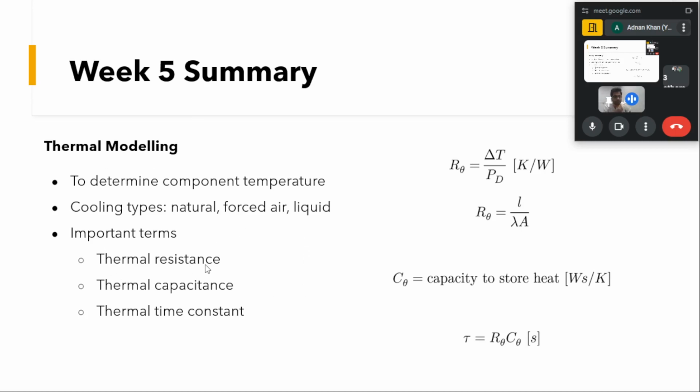First is thermal resistance. This is the thermal resistance of the device. If we have a device or the heat sink, in the data sheet these resistances will be provided, and this is nothing but the ratio of the difference in the temperature change and the amount of the power loss.